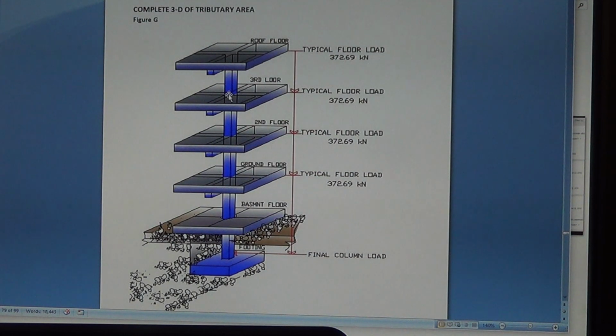And that's the most important load that the foundation is carrying. Never mind the live load. Sometimes there's no live load there. Live load is like a moving load. Sometimes it's in there, sometimes it's not there. What is the static load that the foundation will be carrying throughout its life? It is all these concrete loads here, floor by floor, column by column. Once you reach here, you're ready to get the final column load. Then you can do the foundation design.